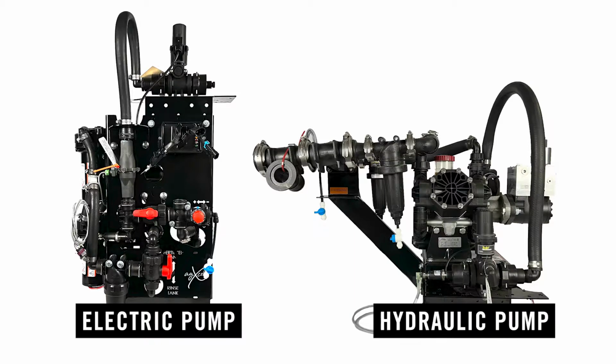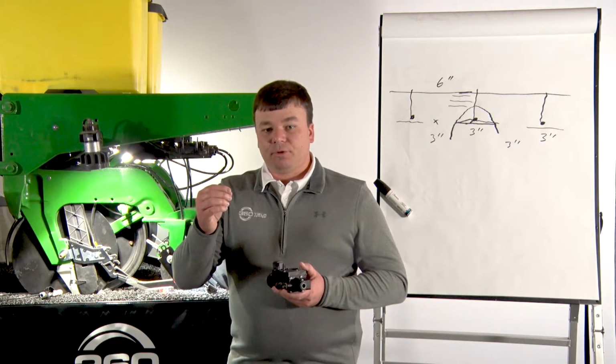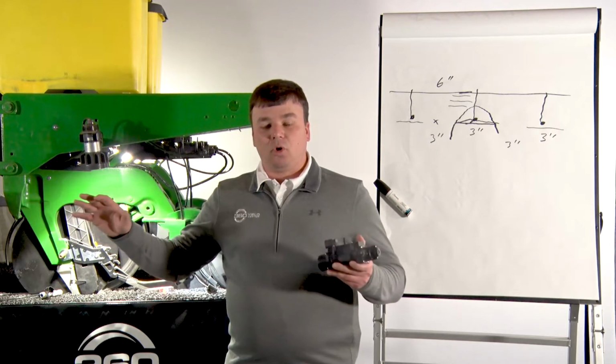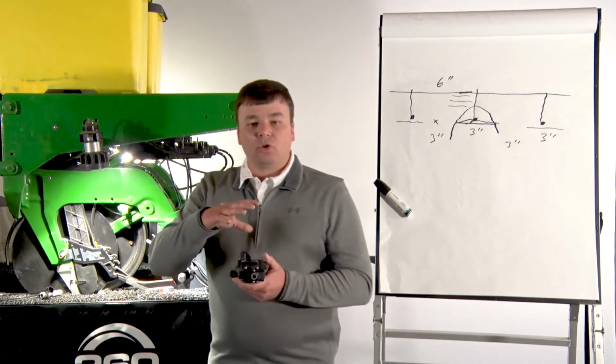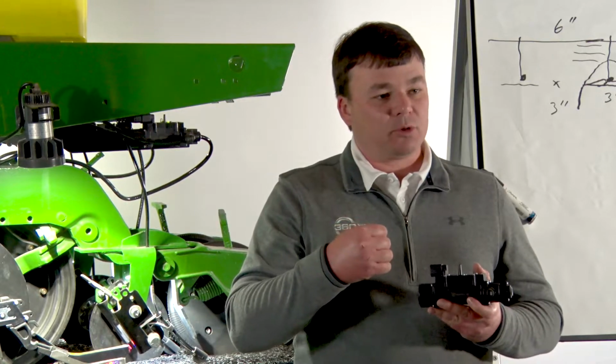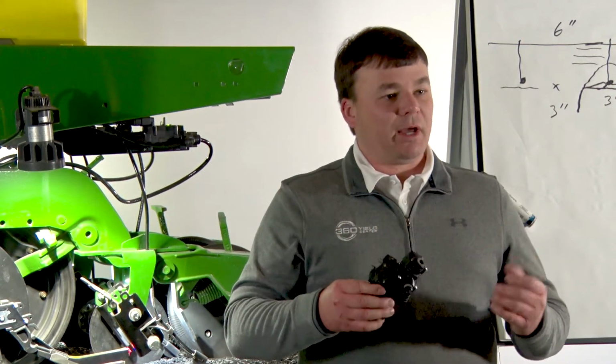We also add a pump to your planter that we can then control, again, with our central command system with the iPad through what we call our hub. We run the pump, and we can then set a target pressure in the iPad, and we want to maintain that consistent pressure across the whole planter all the time. All the rate setting is done in the valve itself by how far we open it up as we're passing over the seed. So let's take a look at the iPad itself and show you what that user interface looks like.